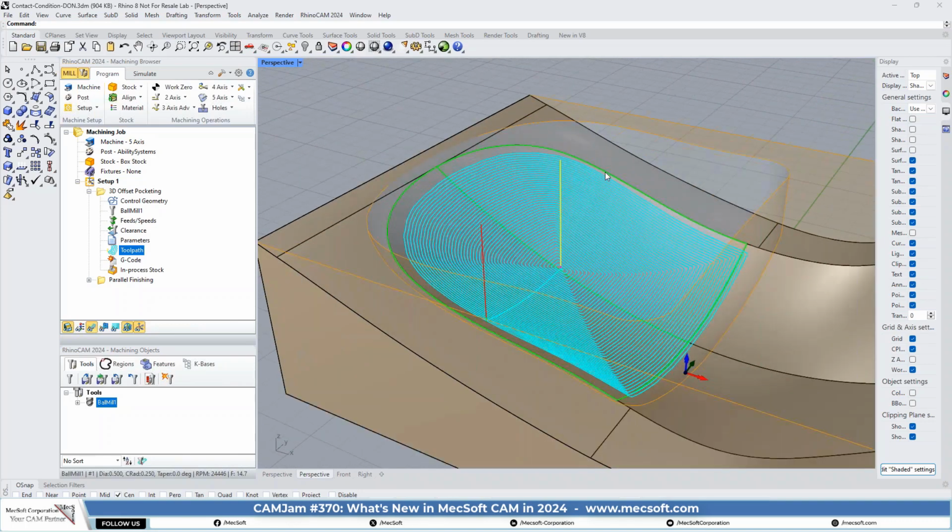So anyway, that's just a very good option for mold makers to get a real clean cut on that parting line. What I was going to say is before this, what we normally would do is untrim these surfaces, extend those surfaces out so the tool could just ride past the parting line. But that adds extra tool paths, that adds extra modeling time. If you don't have to do it now, you don't have to. It just stops right at the contact point.